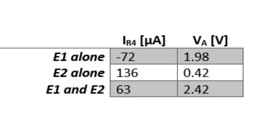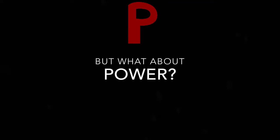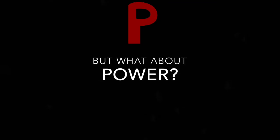When adding together the values we get from E1 alone and E2 alone, we almost get the same result we get from E1 and E2 with a small deviation. This states that superposition can be used to find total current or total voltage. But can superposition be used to find the total power in the circuit? The short answer is no.